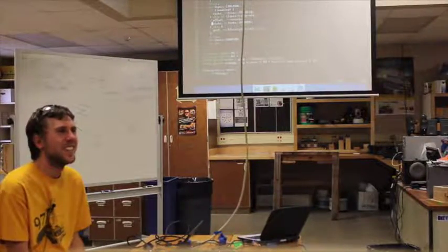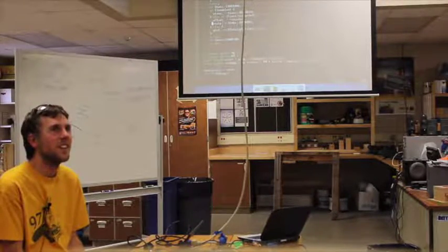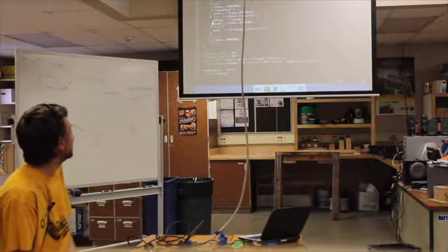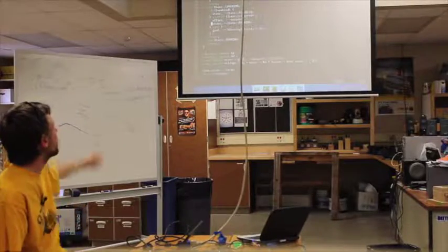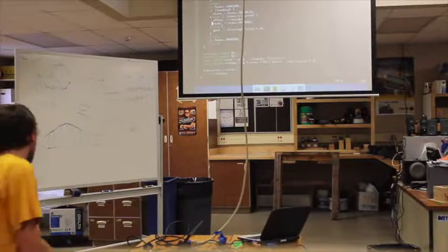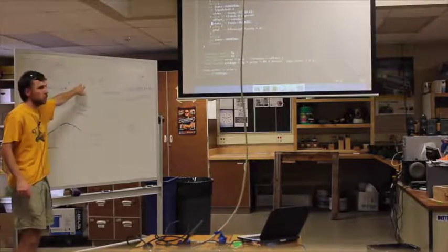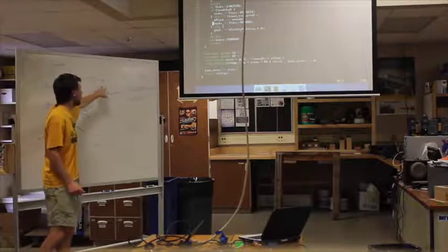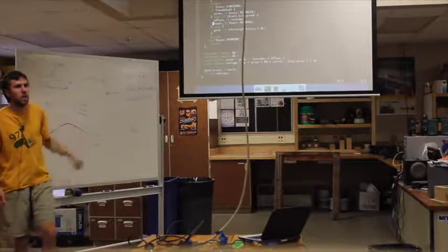I don't know what's happening enough. Okay, so what part have I lost you at? I think all the stuff you covered in the first one. Okay. So this is a piece of code. We have a state machine here. We start out disabled. On enable, we go to a lowering state, and then we slowly move a goal down. And then when we've found the Hall effect, we go to a running state. You can see that in the switch statement there.